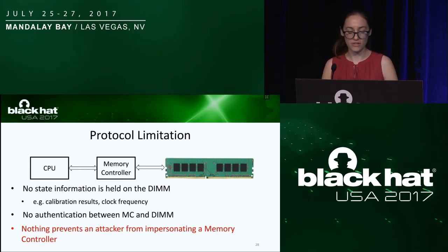So overall, the protocol limitation that we have identified is that really there's no state information that is held on the DIMM. Everything is held on the memory controller side. So the calibration results, the clock frequency, all of them are stored in the memory controller. And the other most important thing is that there's really no authentication between the memory controller and the DIMM. So really nothing prevents an attacker from impersonating a memory controller to the DIMM.